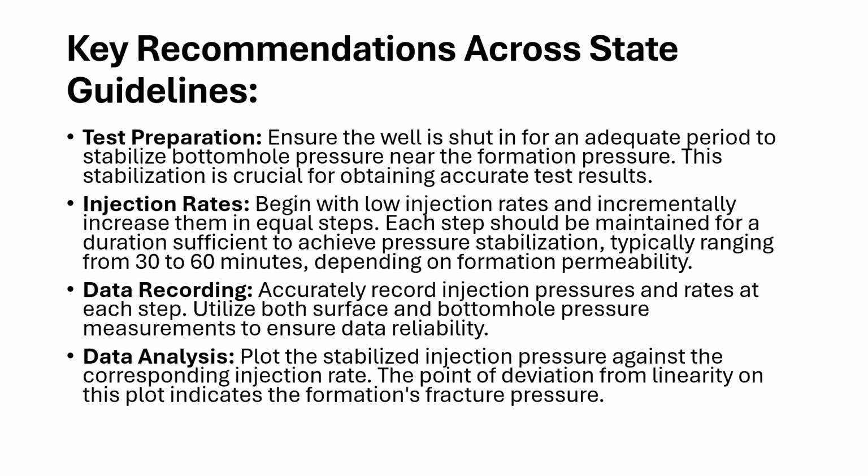The states typically require data recording, a record of the injection pressures and rates at each step. We recommend, and the states do too, that you utilize both surface pressure and bottom hole pressure measurements to ensure that the data is reliable. And the analysis requires that you plot the stabilized pressures against the corresponding injection rate. The point of this is to find the deviation from linearity on the plot, and that will indicate the formation fracture pressure.